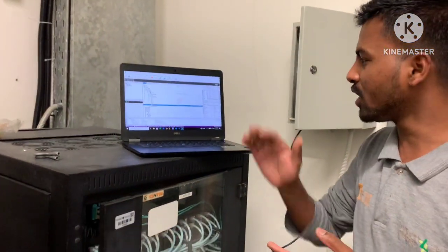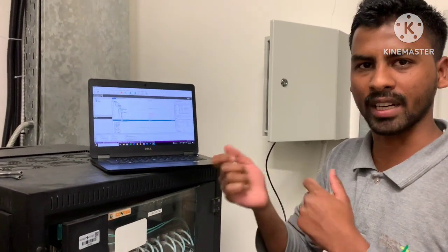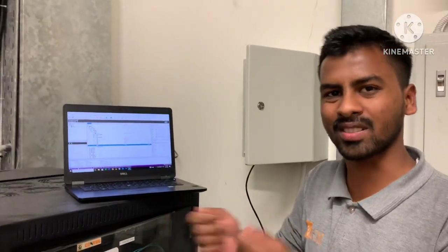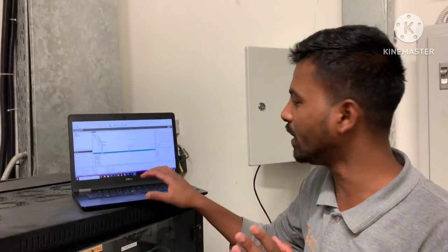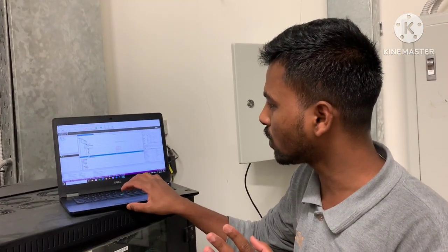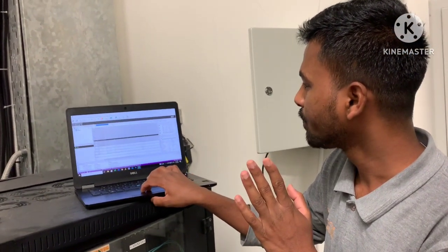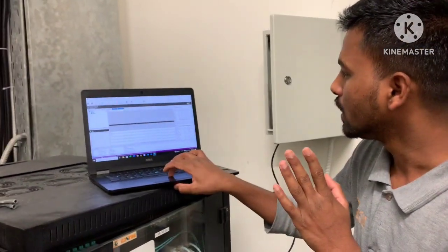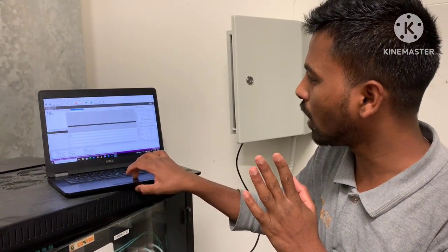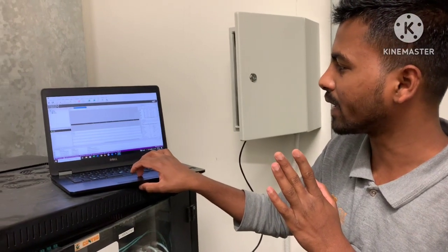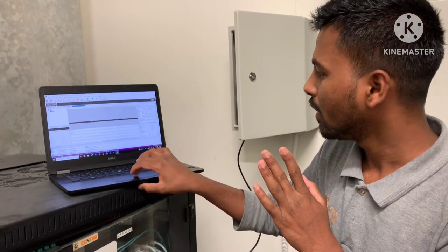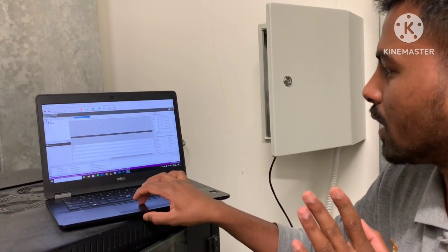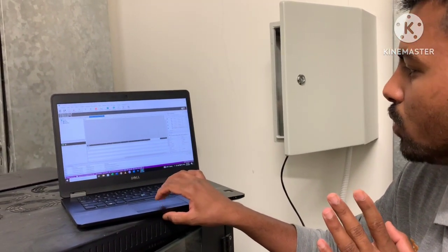So now what is the issue with the program? When I'm restarting my server, it's not going to read automatically. So what I will do, I will enable it so that once we restart our server, it must read by itself. We don't need to read it manually. Just go to your data points, and there you will find a column that is showing read on reconnect. Just enable this point as true. For this read on reconnect, just make it true. I will show you how.